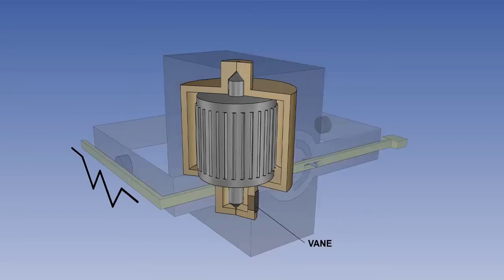In the air-driven artificial horizon, the spin axis of the earth gyro is tied to the earth vertical by a system of pendulous vanes and air jets. Any tendency for the gyro to topple is counteracted by the precessed reactive force from the air jets. The centre of gravity of the gyro is also kept below its pivot point on the inner gimbal to assist in keeping the gyro vertical when not in use. Let's look at how it works in more detail.